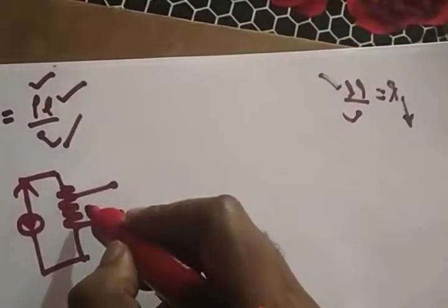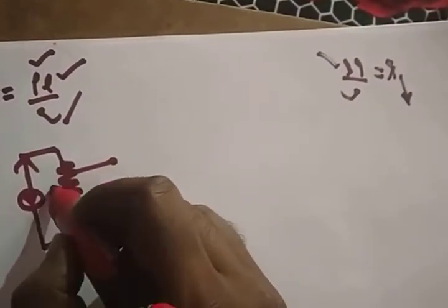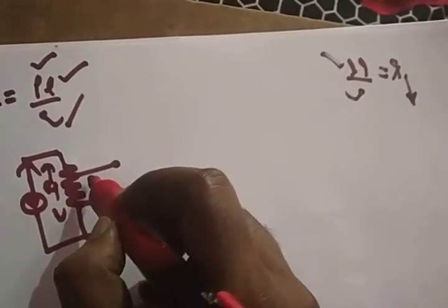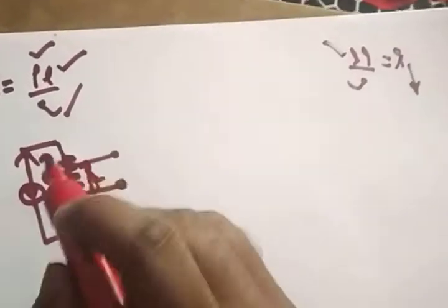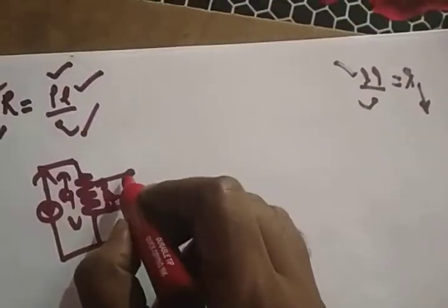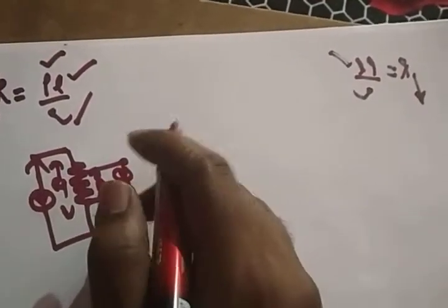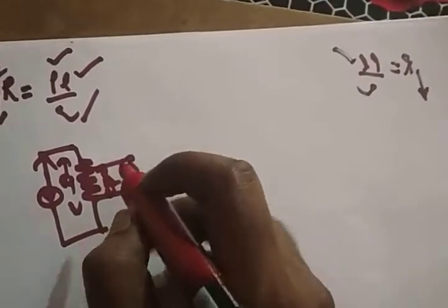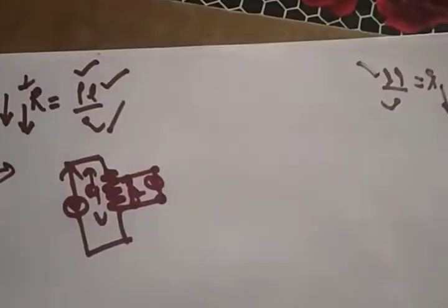Whatever the displacement is, there is a changing resistance. Suppose it is R1, and when you create a displacement, the resistance changes to R2. Now, knowing the calibrated scale, the voltage you read on the voltmeter is equivalent to the displacement itself. So the displacement is converted to voltage.